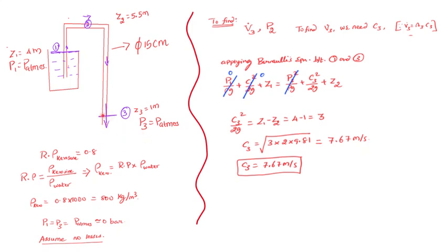But if you think of it, my dear people, the diameter of the pipe is exactly the same everywhere, and the volumetric flow rate is going to be the same everywhere because of the continuity equation, which means the velocity C3 is equal to velocity C2 in the pipe. We'll go to that in a minute.